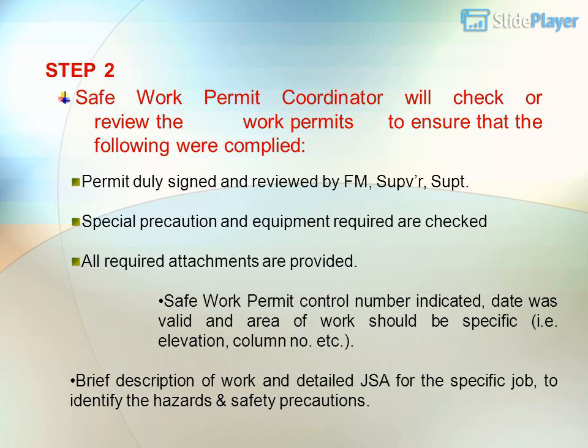Step 2: Safe work permit coordinator will check or review the work permits to ensure that the following were complied with. Permit duly signed and reviewed by FM, Superintendent. Special precautions and equipment required are checked. All required attachments are provided. Safe work permit control number indicated, date was valid and area of work should be specific, i.e. elevation, column no., etc.